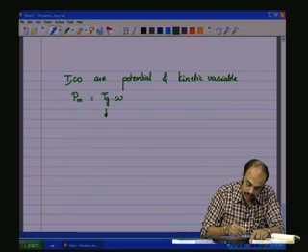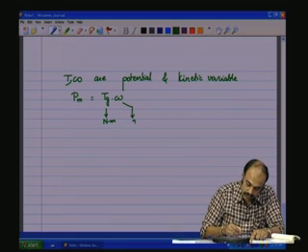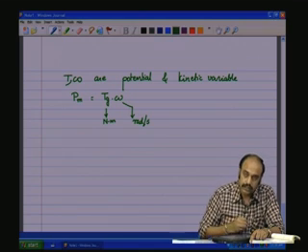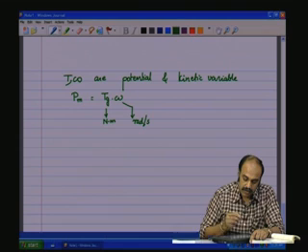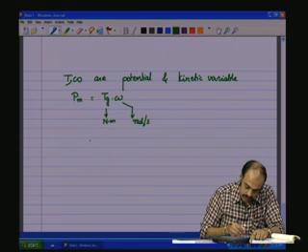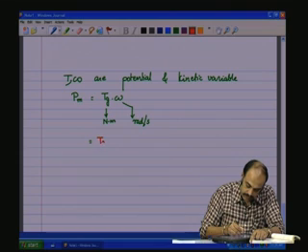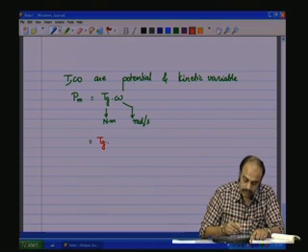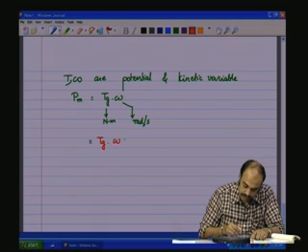Now, this is in Newton meter and this is in radian per second. Let us express the rotation in terms of RPM. So, this becomes Tg into omega, where omega is in radians per second. To convert it into RPM, we are multiplying by 2 pi by 60.